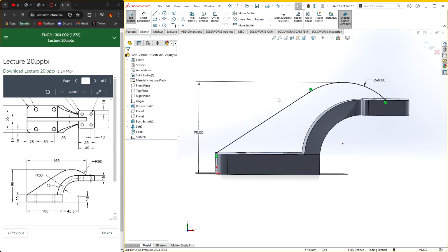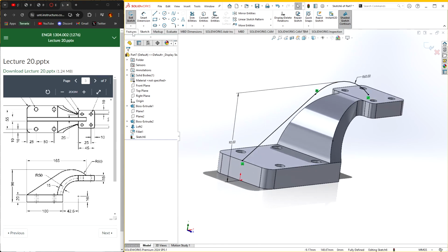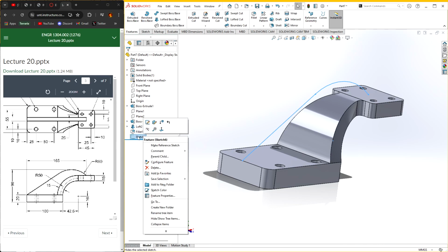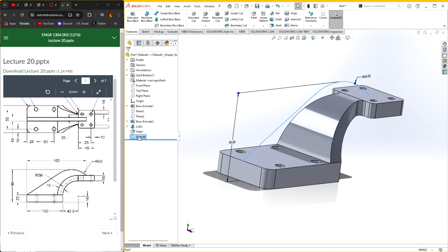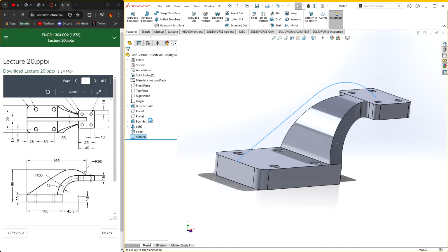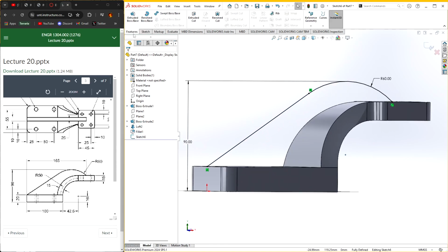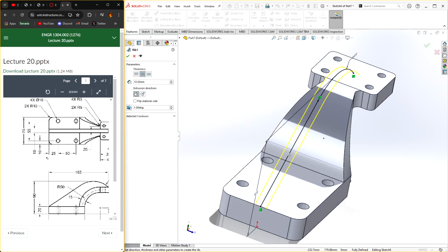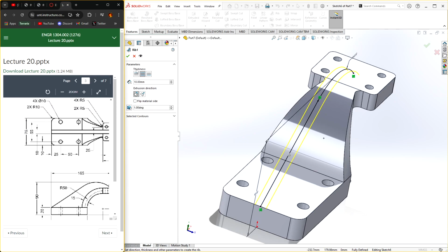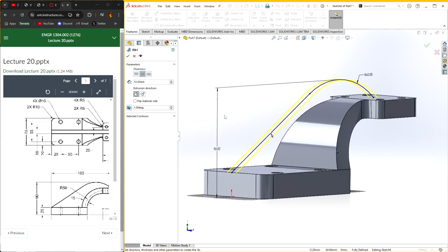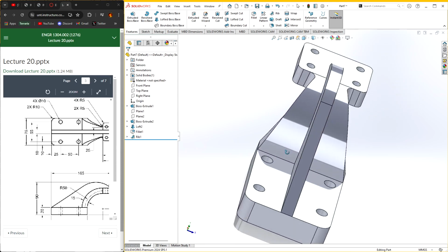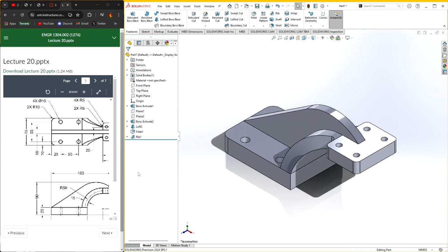Yeah, okay. Because after this, we can exit the sketch and do a, actually, I don't think I was supposed to exit the sketch. Hold on. Go back into the sketch, edit sketch, go into features, and rib. Yeah, there we go. So the width of this rib needs to be 10 millimeters. Yep. So this needs to go on the inside like this. If I just click check on this, yeah, it should work. So this should be your part.